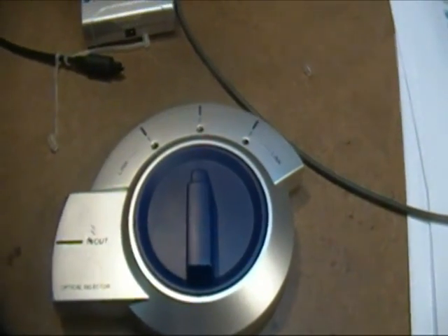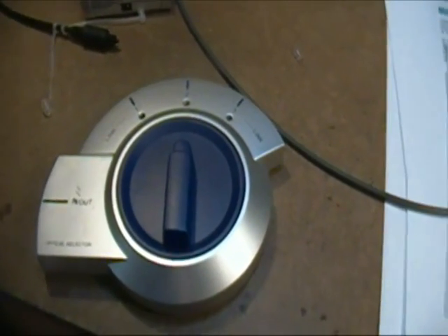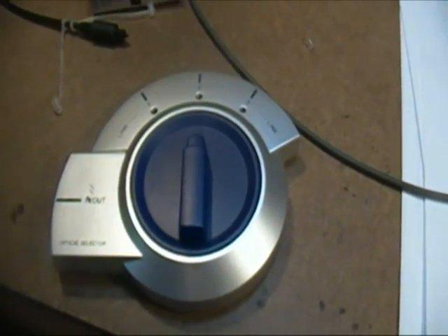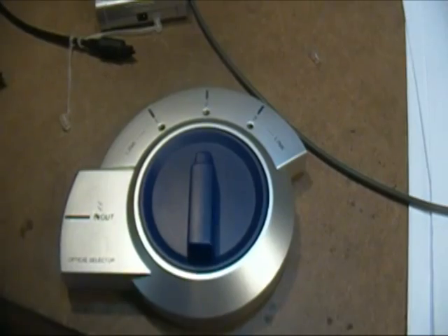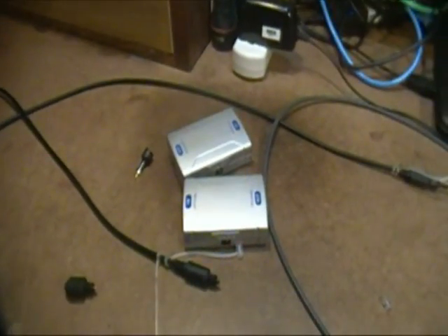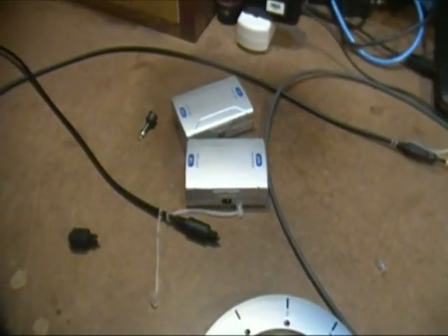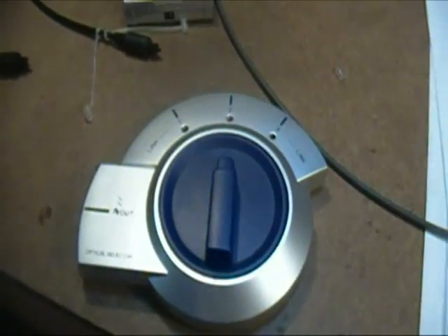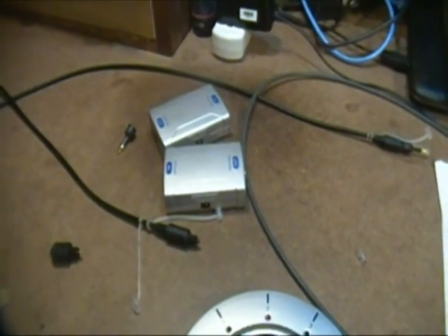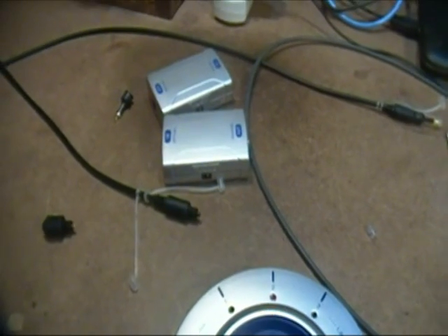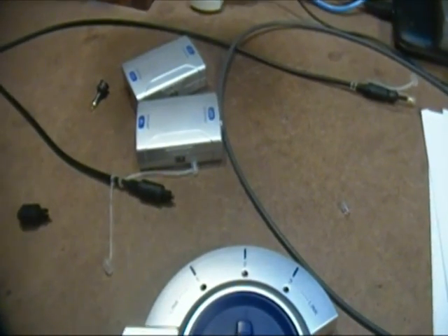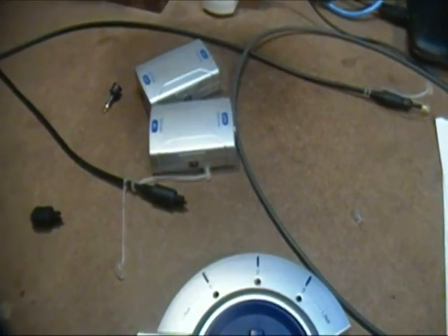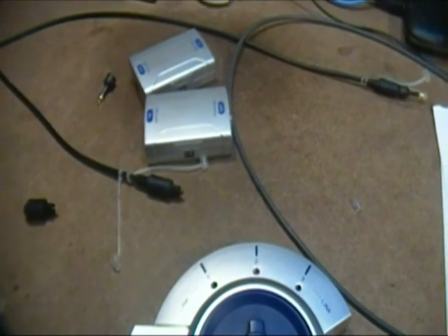So I hope that helps if you're looking for hooking up a Toslink connection, which often you get either out of an HDMI splitter, or, as you saw in one of the other videos in this series, sometimes when you're up-converting a component video system to HDMI, the audio is in the form of Toslink. So you may need some adapters or some switches or other things to convert or configure your system. I hope this helps a little bit in what the various audio digital options are, and is intended as a kind of supplement to the HDMI videos.